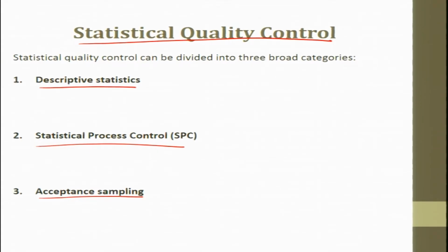Now statistical process control involves inspecting a random sample of the output from a process and deciding whether the process is producing products with characteristics that fall in the predetermined range. So process control answers the question whether the process is functioning properly or not. Some authors, if you read books, would say that quality assurance deals with statistical process control, and quality control deals with statistical quality control.